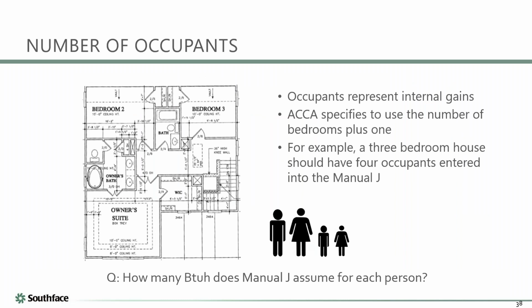And then, of course, how many people are in the house. I may have told you the story, Joey, about the guy who brought me a load calc, and I did it, and I said, well, depending on assumptions, it's either 1.5 or 2 tons. And he started laughing, and he goes, well, somebody else did a load calc for me, and they said it was 3 tons. And I was like, oh man, maybe I screwed up. And I said, can I see theirs? And I looked at their inputs, and amongst other things, Atlanta had a design temperature of 105. They had 15 people in a 3-bedroom house. So those are great examples of ways to fudge your results. You don't know, they could have had 15 people in the house. It could have been a party.